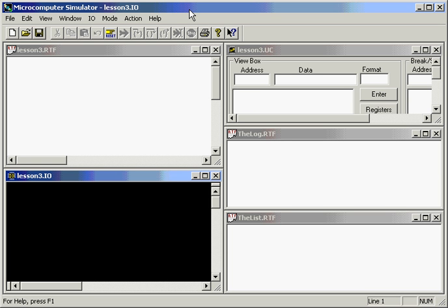outputs to an LED. In the previous two lessons, we created a program file, for the source code, and a microcomputer file, a .uc, for the information inside the microcomputer. However, electrical and mechanical devices that exist outside the single-chip microcomputer will be defined in an I/O file. In this example, we will connect a switch for the input and an LED for the output.